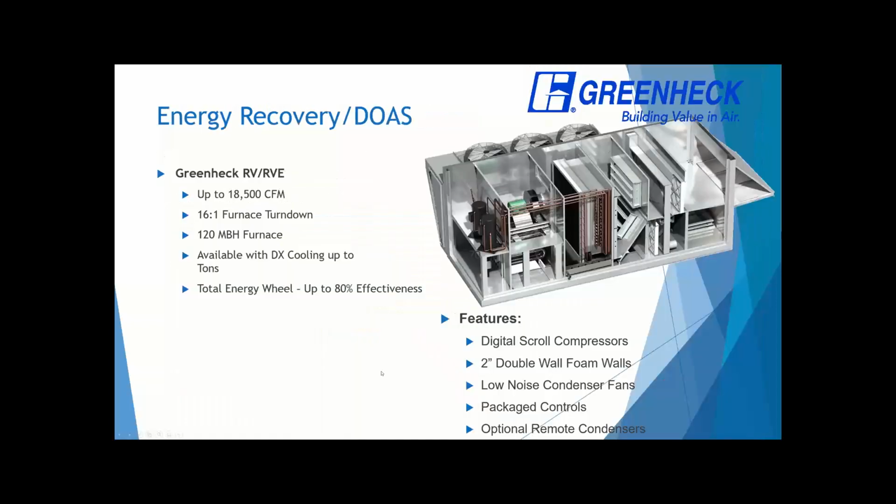Finally, I want you to know that we can provide the equipment on these projects as well. It's really important that you get that equipment correct so that you're supplying that 63 to 68 degree air with dehumidification. In a typical application, we could provide something like a Greenheck energy recovery DOAS unit, a Greenheck RVE, with energy recovery. We can do it without energy recovery, but the whole point of this is to cover energy. So we could provide it like this.